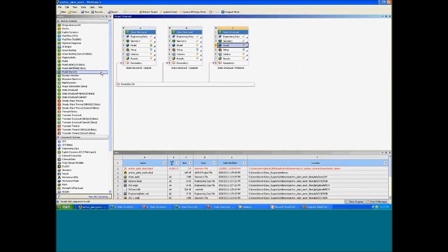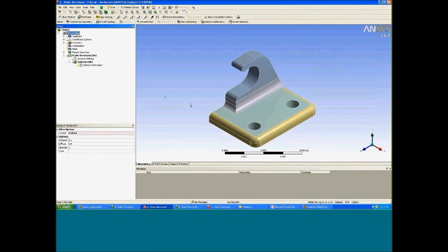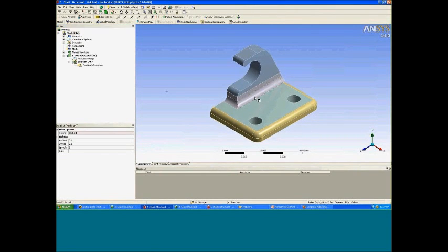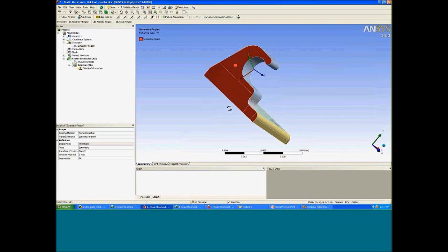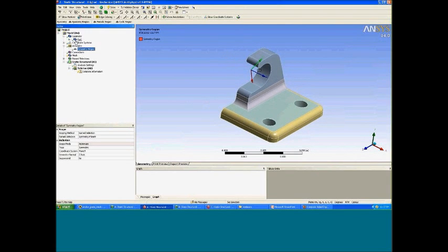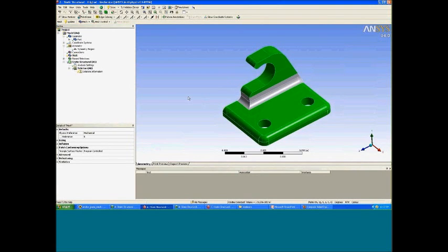bring that over, and I right-click on the model and refresh to read in the new geometry, you see I get updated so that I have the same geometry and meshing that I have in Design Modeler. Now I have the symmetry conditions on this region here where I used the symmetry tool. My geometry shows I have a multi-body part. And if I right-click on meshing, it shows me exactly what I thought when I was doing the slicing. I have 3 sweepable bodies.